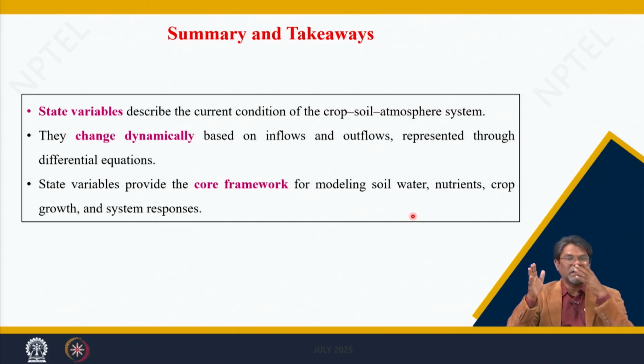This understanding is represented using the Forrester notations, or compartment model symbols, to represent the flow of water from tank 1 to tank 2 and out, and what parameters influence the flow rate, like area or the proportionality constant C1 or the gravitational constant C1 G. That is also explained here.